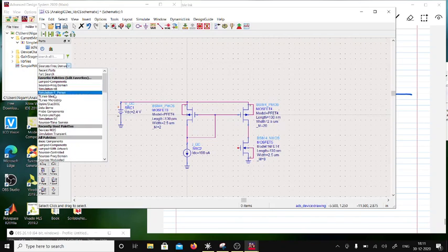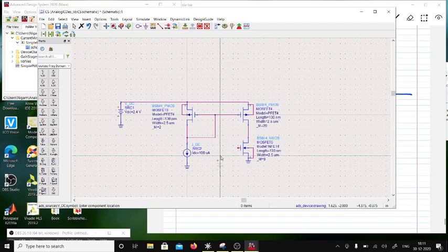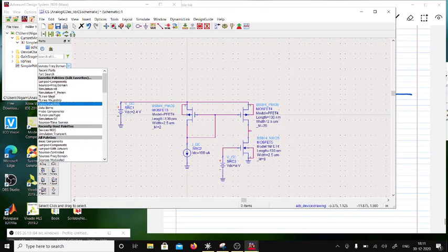Okay, so I am going to put a DC voltage here. Sources, frequency domain, DC, and I'm going to sweep this from 0 to 2.4 volts. This input I will call VI, and this node voltage I will call VO. I want to plot VI versus VO while sweeping, so I'm going to do a DC analysis on this.